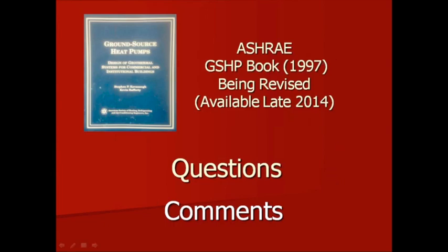David's question, Steve, is my experience of ground source heat pumps is that the hydronic balancing of the primary and secondary loops is paramount to optimizing performance. And this is something that is not always understood by the contractor, the installer. Is this your experience, Steve?